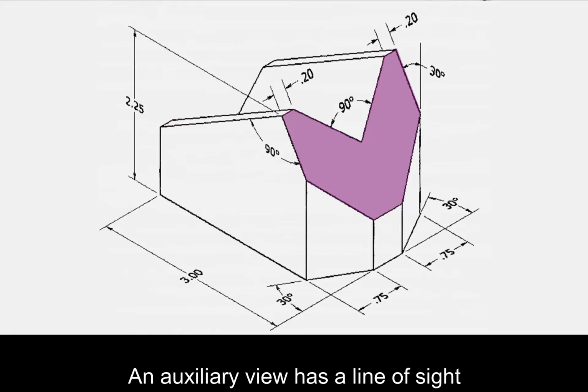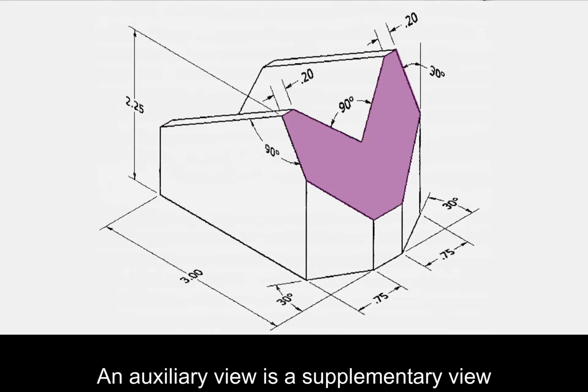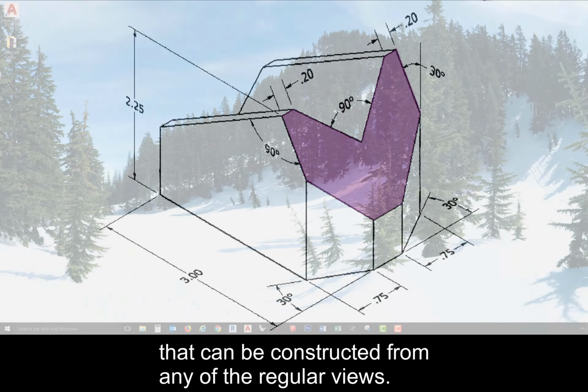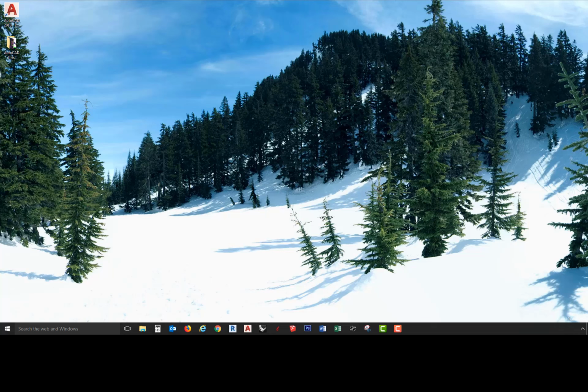An auxiliary view has a line of sight that is perpendicular to the inclined surface, as viewed looking directly at the inclined surface. An auxiliary view is a supplementary view that can be constructed from any of the regular views. This lesson will demonstrate the construction of an auxiliary view using various CAD techniques.